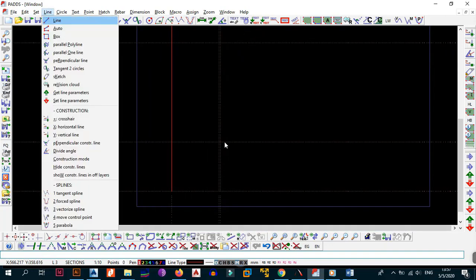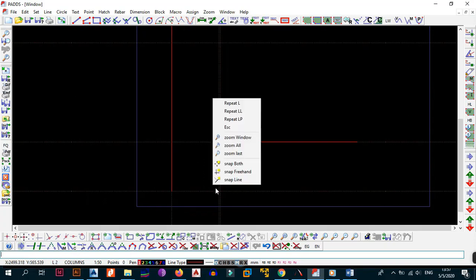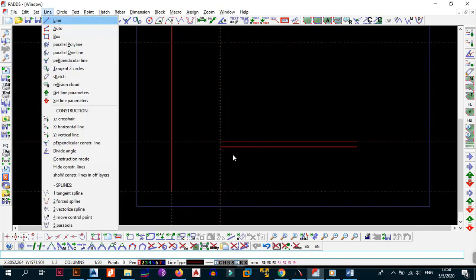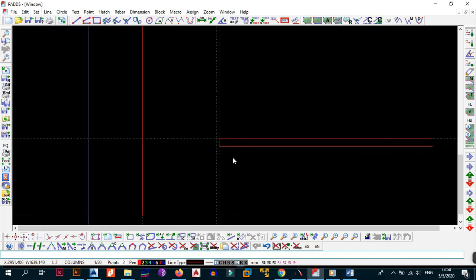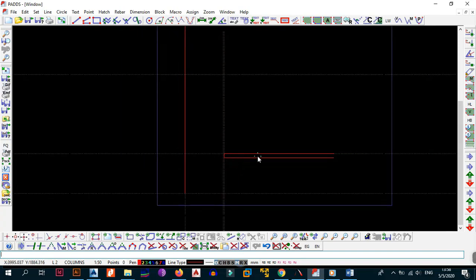Then what you need to do is create a line, because your slab will be disjointed from the actual column. And then the next thing that you want to do is go back to layer 2. Then what you're going to do is LP this by 150. All right. Then create another line there to join it, because remember, in the vertical we are keeping a scale, but in the horizontal we are not. So that will represent the slab.